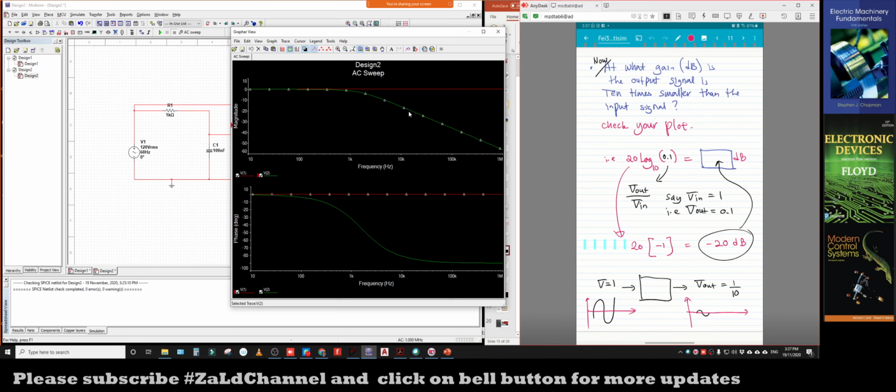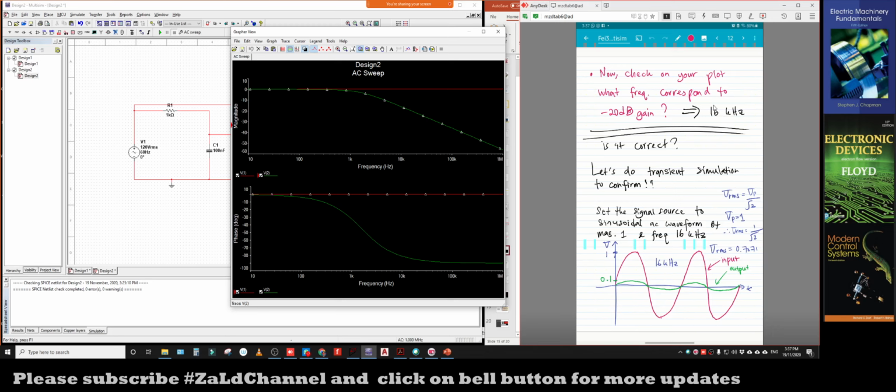In this case, we cannot clearly identify this because we are using Multisim. If we use LTspice, later I will show you the same simulation, where we can trace that negative 20 decibel is actually 16 kilohertz. When the output signal is 10 times smaller than the input signal, the magnitude is negative 20 decibel. If we trace the frequency of that signal at negative 20 decibel from this graph, it is 16 kilohertz, somewhere around here.